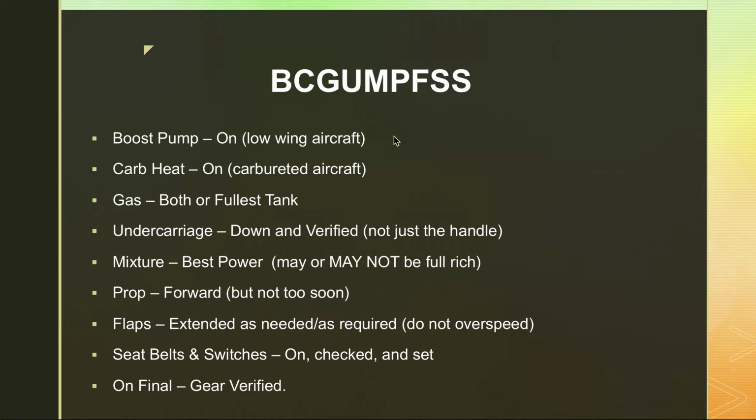Flaps. You'll get in the habit of checking your airspeed before you extend your gear. You should get in the habit of checking your airspeed before you extend your flaps. And it's just going to become more important the more complex aircraft you fly, because they might have different speeds for different flap settings.